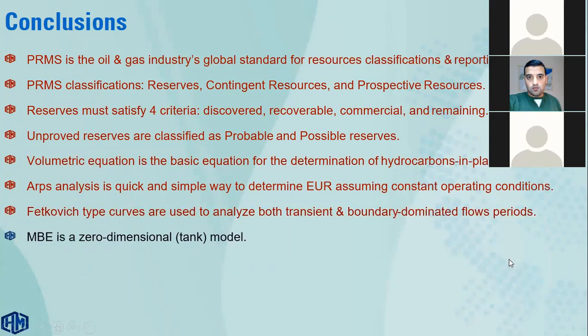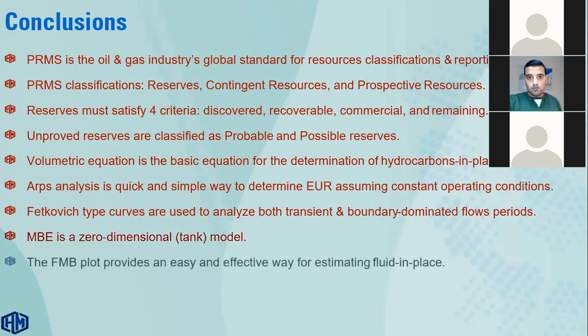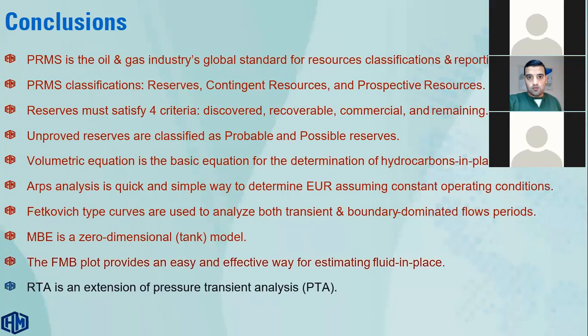Material balance equation is a zero-dimensional tank model and an analytical reservoir engineering approach. Flowing material balance is a technique that provides an easy and effective way to estimate reserve and hydrocarbons in place. And finally, RTA, or rate transient analysis, is an extension of PTA, or pressure transient analysis, used to get the reservoir properties and calculate reserve.